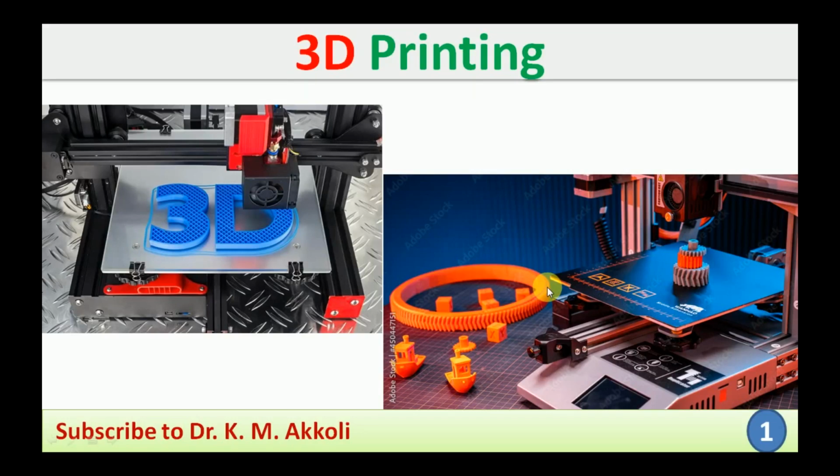Till now in the manufacturing industry, what process was followed? That process was casting through the foundry industry. The casting of the particular component is manufactured first, and later different machining processes are carried out, like gear teeth cutting, keyway cutting, and some dimension reductions. All these things are carried out on that component. Then the finished product is tested for its function as well as performance.